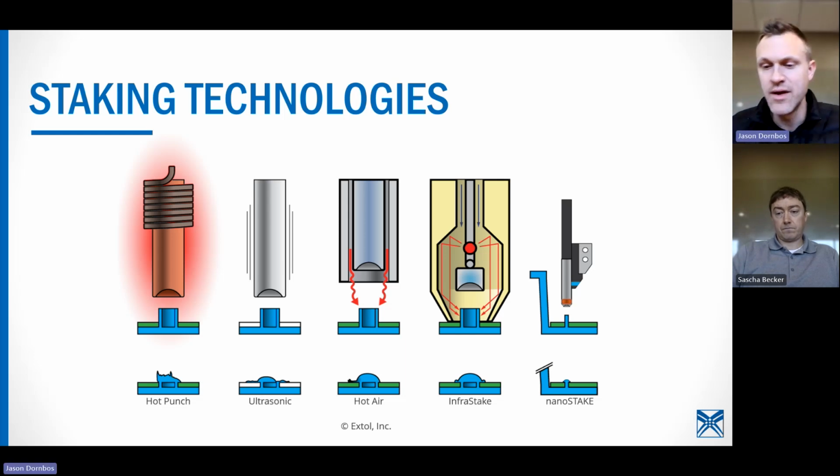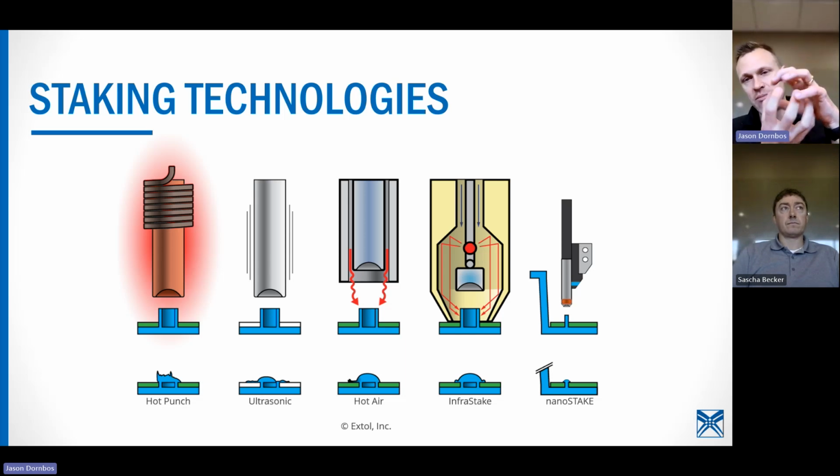Can it be waterproof? Staking is not usually considered waterproof. If you had a hollow boss and you were filling something and then you staked that hollow boss shut, that would be a hermetic seal. But usually, if you're going to bond one component to another, you would have to have some kind of a gasket between those components. And then when you stake them, you're trapping the gasket, which creates the hermetic seal.